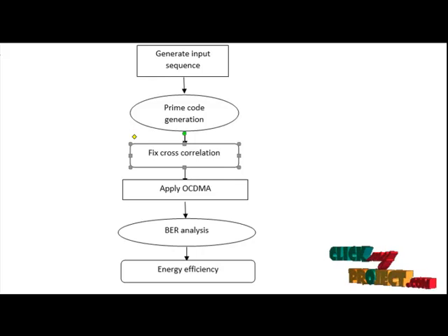Correlation is the process of finding the similarity between 2 signals to recover the original signal. We can use any modulation codes to modulate the signal, but we should choose the best code that results in good separation of the signals between the 2 users. Separation is done by correlating the received signal and the modulation codes.